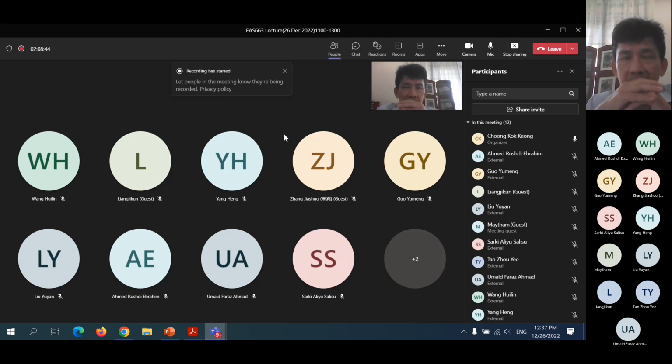When you apply loading, when some deflections in the building model suddenly increase a lot, so we use that loading as to approximate critical load. Okay. So that is the method that we have gone through.